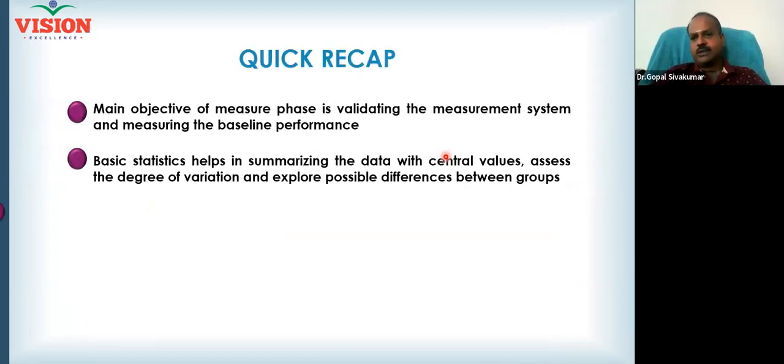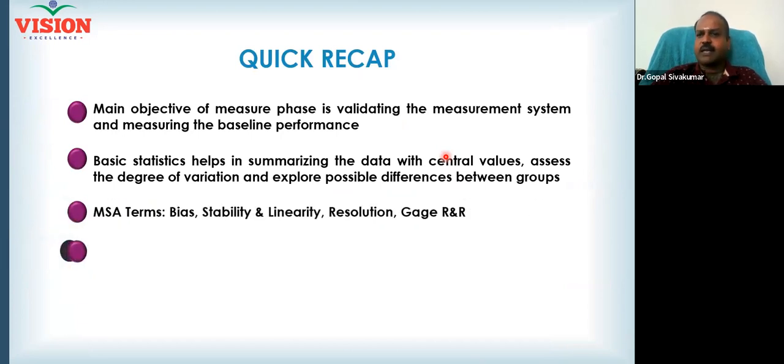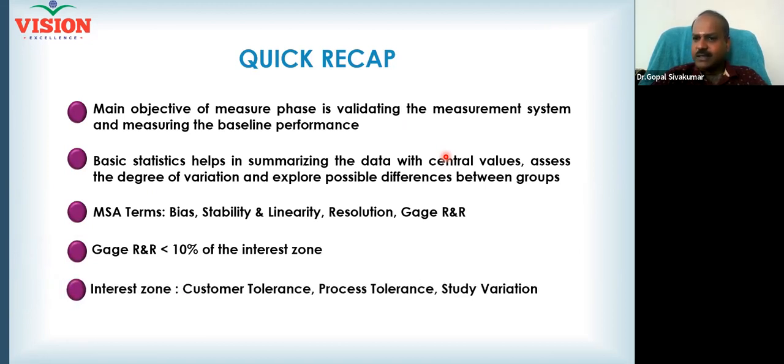Now you are well equipped to take actions and bring down the error. Whether it is repeatability that is pulling down, reproducibility that is pulling down, the product that is pulling down, or a particular appraiser who is pulling down, you create your own guidelines. The guidelines are keep mean equal to median. The guidelines are minimum 10 parts. The guidelines are 50% good, 50% bad. All these guidelines you should set. Only you should know. Other members involved in the study, the operators, should not know about all these things. Do you get my point?